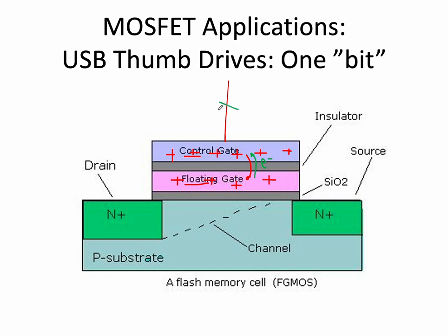Even when you disconnect, this floating gate has positive charge on it, which means this whole thing attracts electrons down here, which means this thing is on, or is a conductor, which means we say that it stores a 1 bit, a true bit.